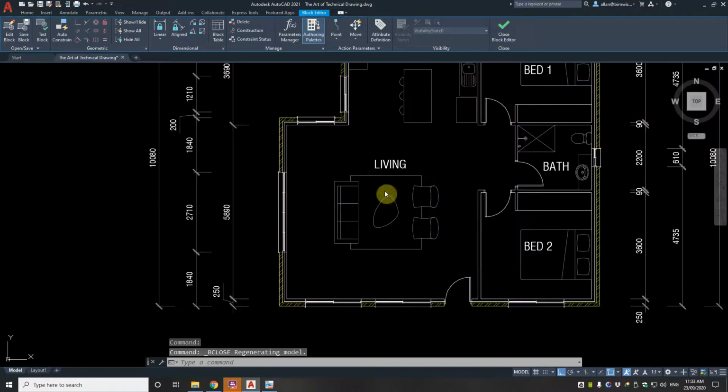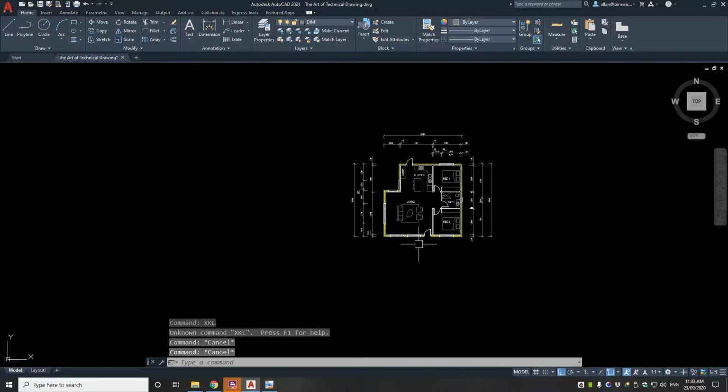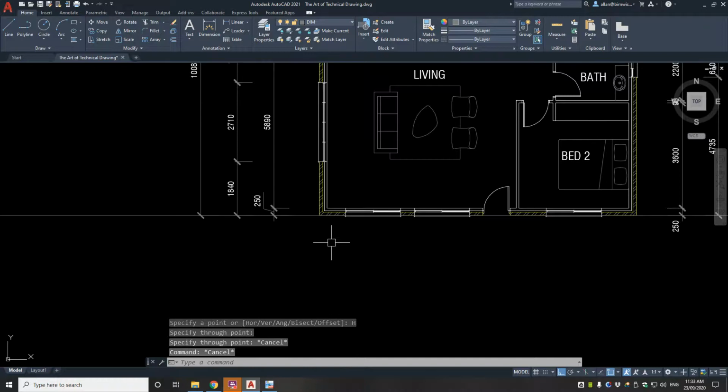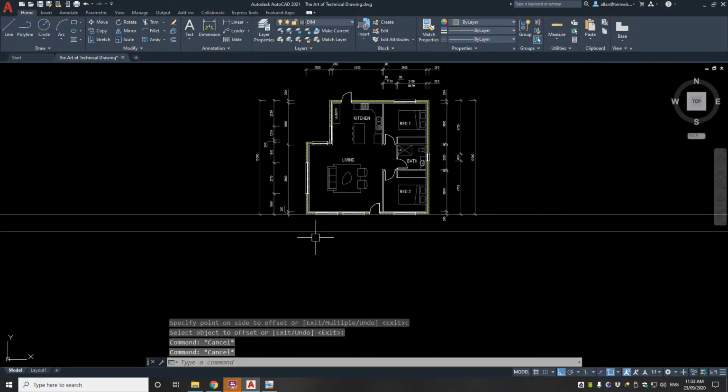Or you could just type in PDMODE and set it from 64, which is the shape I normally like to use for points, to 0, and then they won't show up at all. So you do occasionally get that in blocks, especially older style blocks. Some blocks have been drawn years ago, but they're still good. So they might have some older stuff in them still.